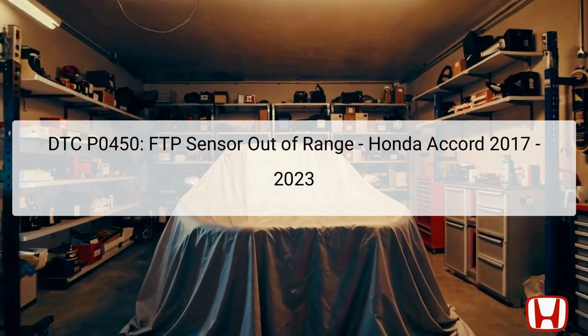This presentation addresses DTC P0450, signifying that the fuel tank pressure (FTP) sensor is registering voltage readings that fall outside of the designed operational range in a Honda Accord from model years 2017 to 2023. The fuel tank pressure sensor plays a critical role by monitoring the pressure levels in the fuel tank, which is essential for managing the Evaporative Emission Control System, EVAP.